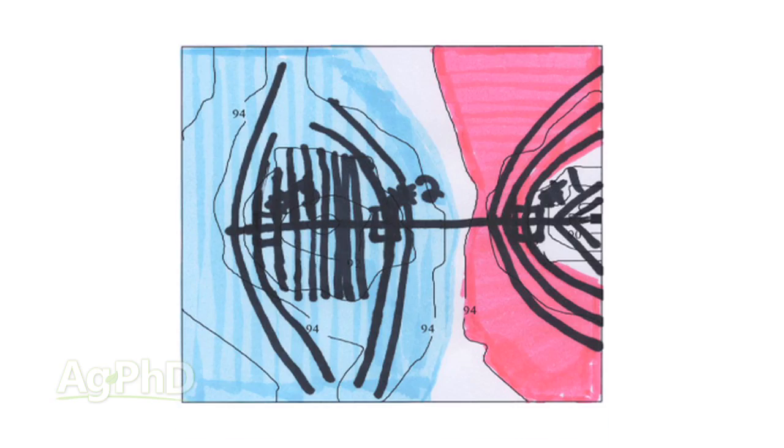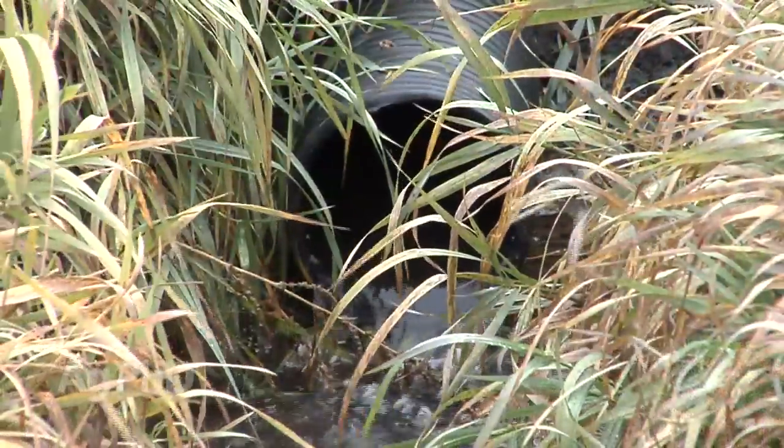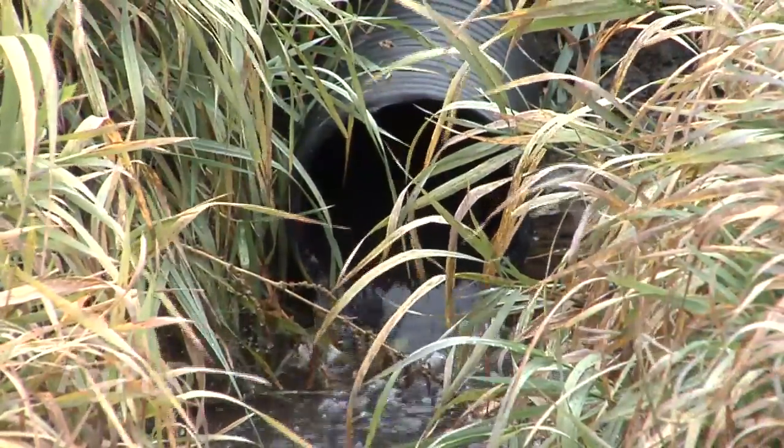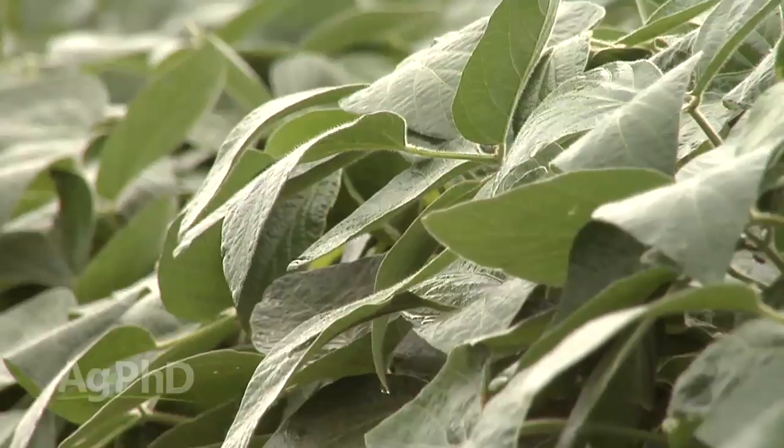What we've done on our farm and what we advise farmers to do all over the world is put in basically like a mini drain system. So have a bunch of tile lines in your potholes in your field, have a bunch of tile lines close together, maybe 15 feet apart or something like that, and a little bit more shallow, so you can get water out of there fairly quickly. Yes, it's not going to be as fast as an inlet, but it's much more environmentally conscious, and it also creates a bigger reservoir, because usually what we see is most guys just run one tile line right to the center of that pothole. Well, wouldn't you rather have about 10 tile lines all running through the entire area of that bowl? Sure, you're going to have a lower water table then, and that way when you do have rain, you have more holding capacity there, so the need for having an inlet is less.